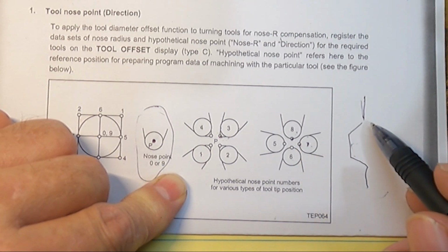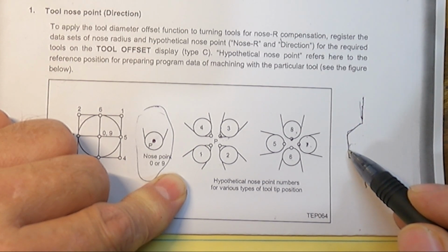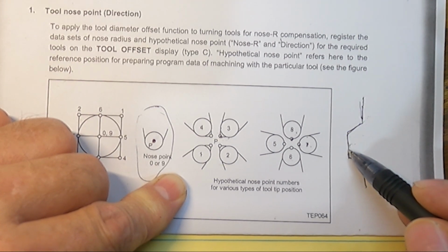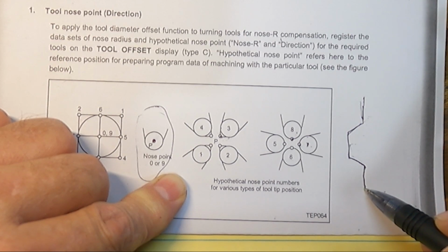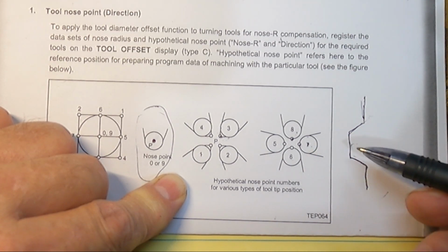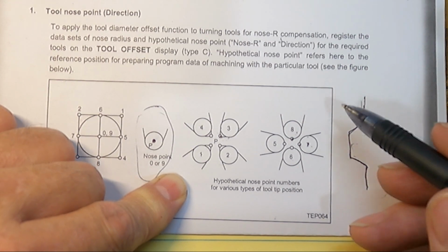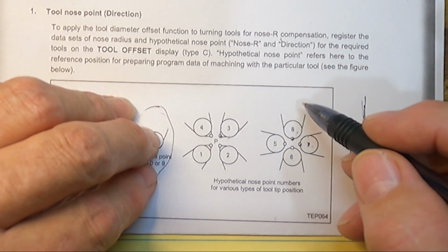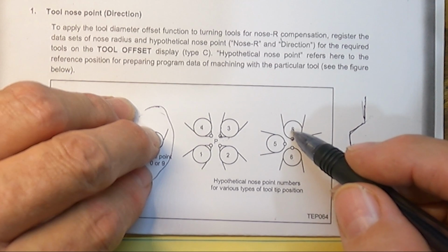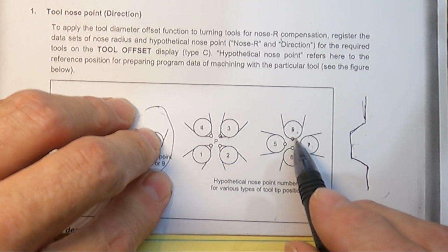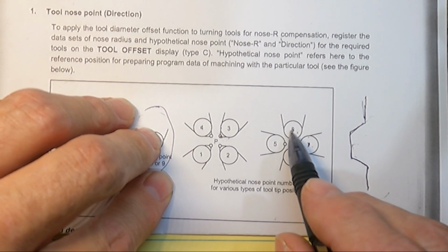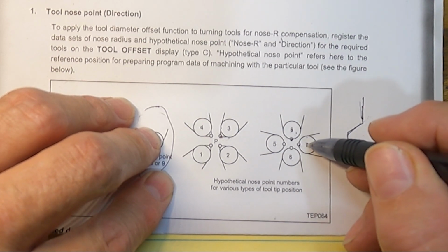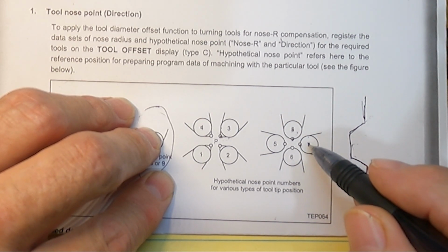And these are handy if you're taking a finished cut like I drew here, like an API or seal ring groove, where you can come in here and you can go around the actual shape of the part with this offset all in one cut, as one finished cut, using a number 7 if you're on the outside face here. Or if you're turning maybe a pulley with a bunch of V grooves in it, you might want to use this number 8 on your tool. But you would have to be careful to set your Z offset in by the radius of the insert. On this one, you'd have to set your X offset to the center line of the radius.